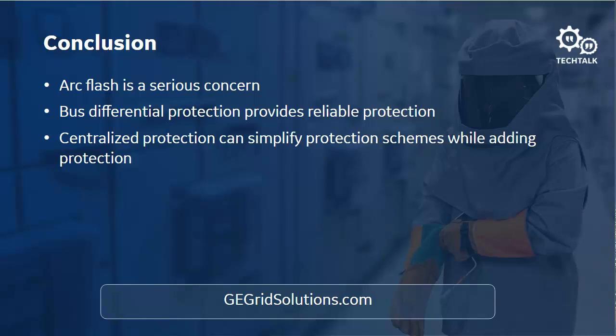The drawback with just looking for light: when arc flash sensors first came out, one of the big things you heard about was people taking pictures of the new application, and the flash would trigger the arc flash sensor and trip the bus. So you need to have it supervised with current at a minimum. Since the light is faster, arc flash light sensors are going to be a little bit quicker than the 87.